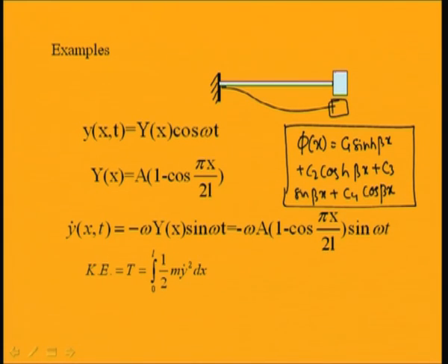As you have added a mass m, the inertia force for this mass will be m y double dot. So this m y double dot will be equal to the shear force, and shear force equals EI del cube y by del x cube. So by taking this generalized mode shape equation and substituting the boundary conditions, you can find the exact frequency function and the mode shape.